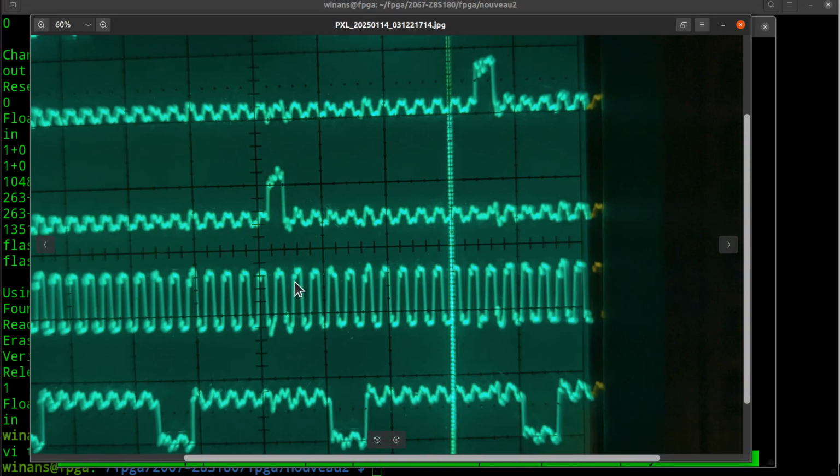Here's the wait state. Here's T3, and the CPU is going to finish its read operation on the falling edge of T3 here. So the read gets done on this falling edge 1 phi clock earlier than the write, which does it over here at the end of the wait state before T3.